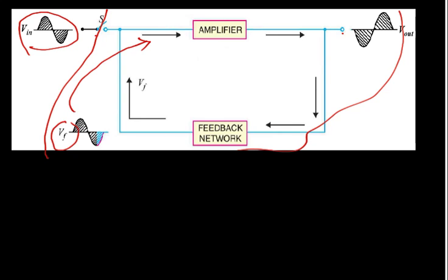So we can say that an amplifier with positive feedback serves as an oscillatory circuit, but we need a trigger to start. Usually this triggering is achieved not by using a signal source, but by using an oscillatory circuit. To produce oscillation in the case of an LC oscillator, we need the capacitor to be charged to the maximum initially. That is achieved by using a battery.